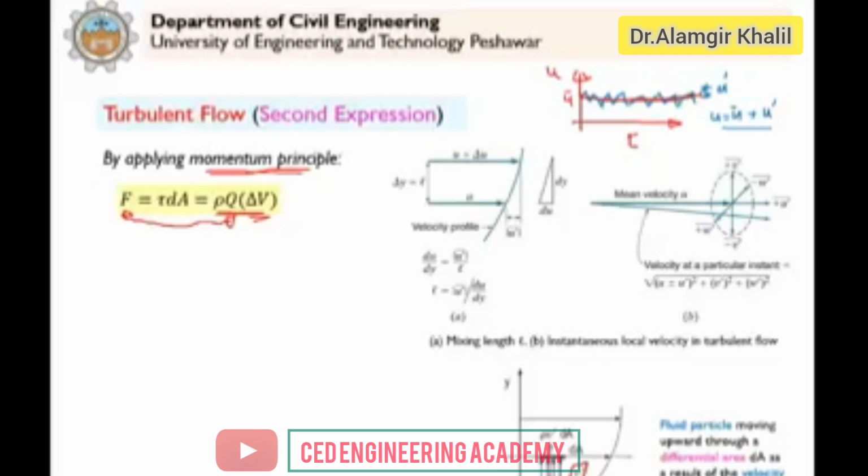Now because of this, there will be a flow of the fluid across this line here. So if we consider this line, we consider an area dA. What will be the flow? We need to calculate the discharge in this equation. Clear? In that case, this discharge will be v dash times dA, because this is the velocity and it is occurring through this area dA.